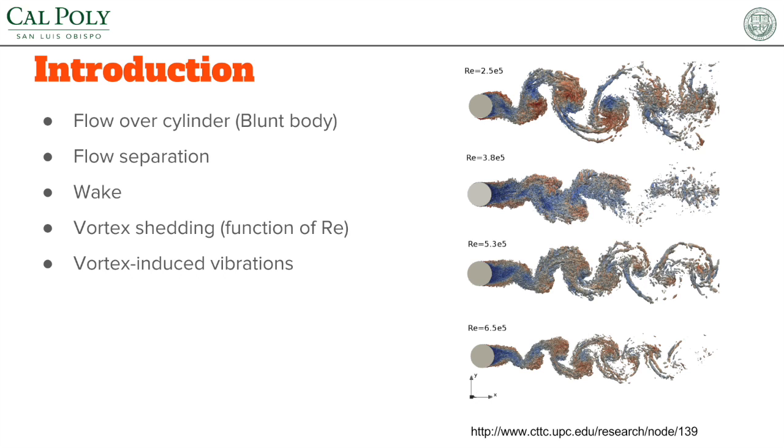The pressure decreases along the front half of the cylinder, with maximum pressure at the stagnation point in the center. However, on the front half, the flow remains attached. In the back, there is a pressure increase where the flow can separate, creating highly turbulent regions called the wake. Vortices are shed by the wake, alternating the detaching location as seen in the diagram on the right.